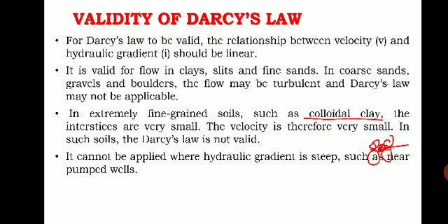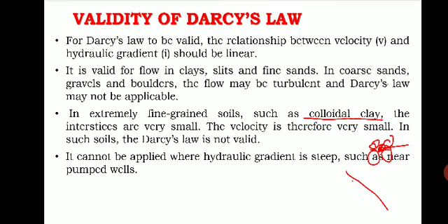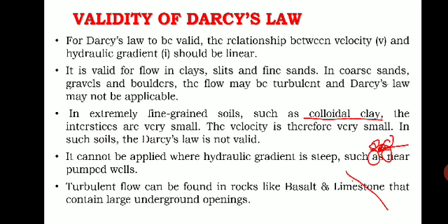Then Darcy's law cannot be applied where the hydraulic gradient is very steep, such as near pumping wells, where the hydraulic gradient will be very steep. The difference in the water level, that is the hydraulic gradient, if it is very steep, then Darcy's law is not valid.